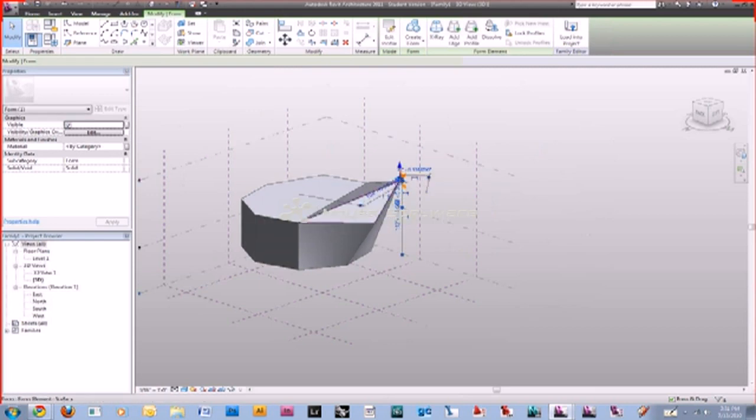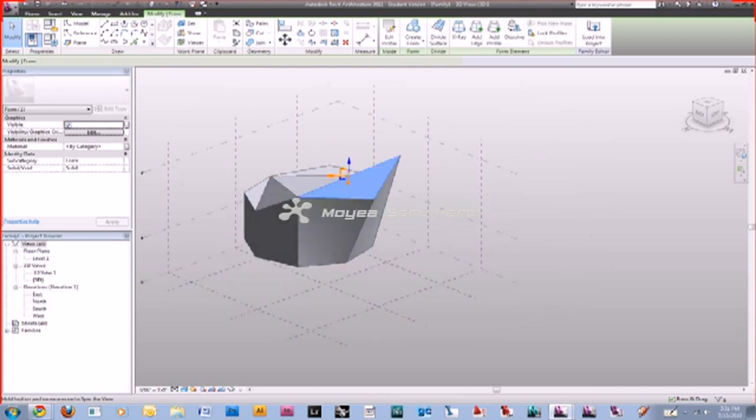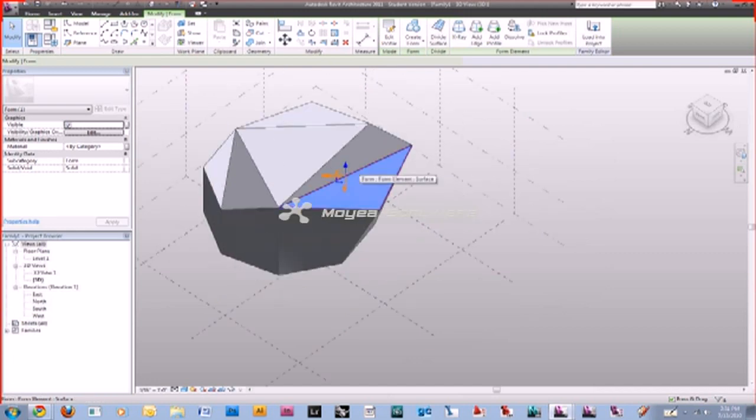There's no sense in adding all the crazy geometry in by yourself when you're just trying to figure out form. So I did notice that if you start editing, say if you had a 20-sided polygon and you're trying to edit each individual line to move in and out, Revit kind of just knows that if you're editing multiple lines, to call out the line first. So once you edit the first 2 lines of that 20-sided polygon, it's going to intuitively know that you're trying to select a line the next time. Just like if you're trying to edit points over and over again, it's going to catch on that you're just editing points, and to give you the point selection first, not just the line selection or the face selection. So it kind of helps you out.